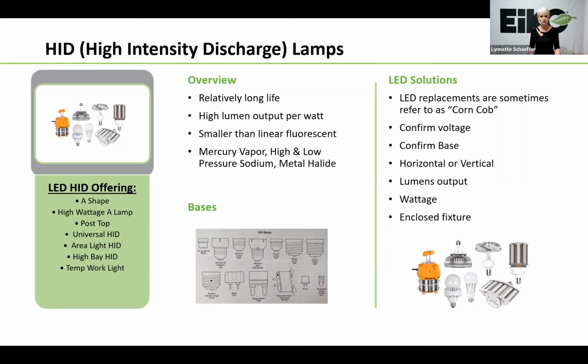Okay. And then the other thing too is that manufacturers also produce LED lamp replacements specific for applications. So for instance, in this particular case, we have a wall pack that is an LED replacement wall pack lamp. These are meant to push the light out, and typically the LED chips are only on a part of a side. That way, when you go to plug that in, you have all the light pushing out the face of the fixture and not the back of the fixture. So again, it's just a way to be as energy efficient as possible.